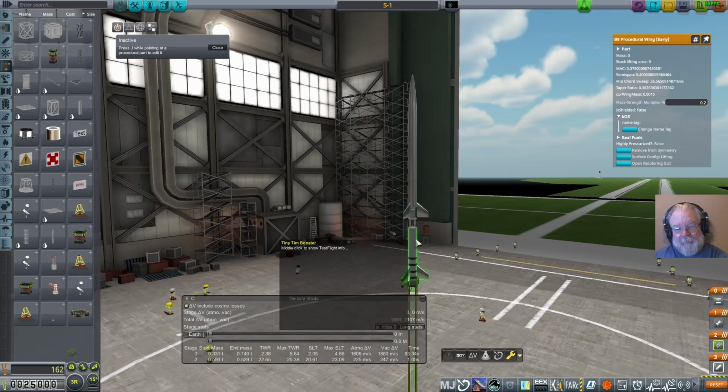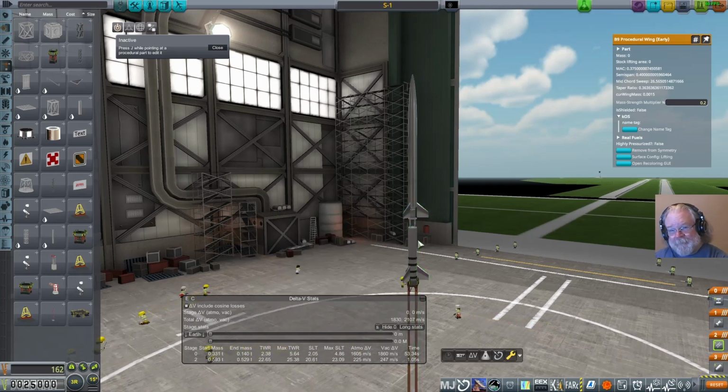So when the thrust gets down below some threshold, we're going to ignite the Aerobee. Then when the total thrust balances out to where the Aerobee is running, we're going to ditch the booster, because the threshold we choose is such that the booster will no longer be producing an interesting amount of thrust at that point.